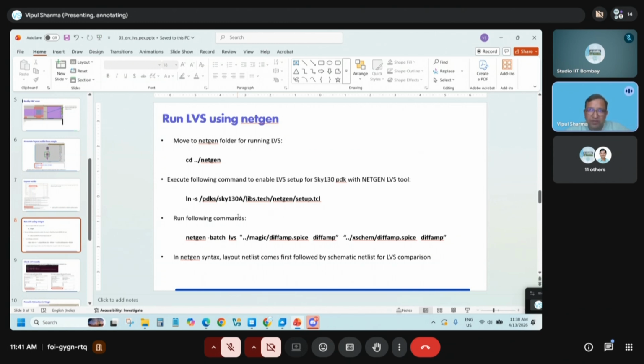But then again, if we go through the complete verification cycle of any typical analog circuit, parasitic extraction also becomes very critical. Because as I said, if designs are big, you expect a lot of connections. There might be overlap, or two nets are very close to each other, so they might interfere. The signals might be interfered because of each other. All those effects are captured in parasitic extraction. So let us now go to this step and see how it is done with our open source flow.